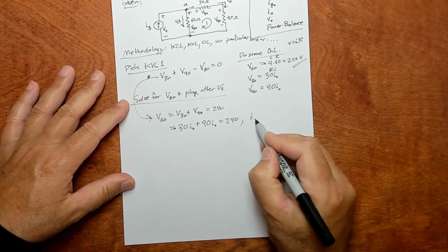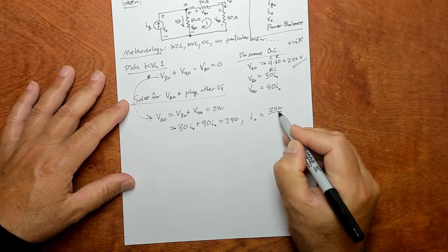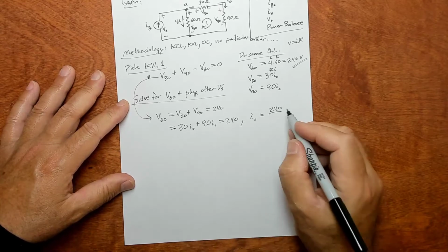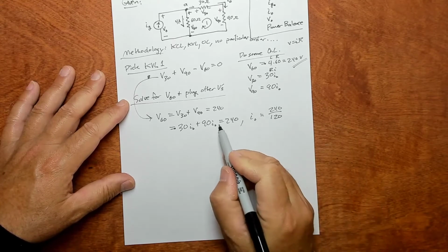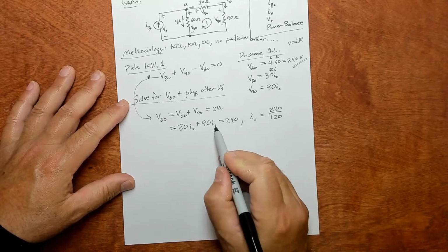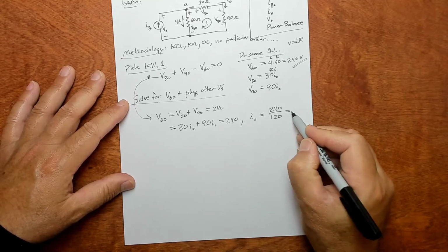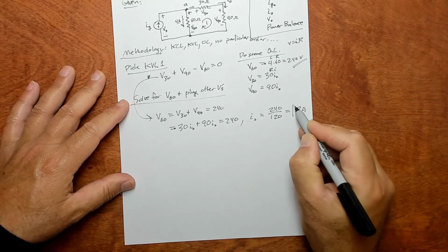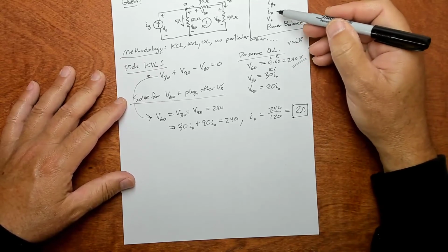So I sub 0 is 240 over these 2, over 120, right? Just factoring out the I sub 0 and then adding the 90 and the 30 and then moving it to the other side, you get this. So it's 2 amps, and that's an answer. So put a box around that, because that's an actual answer that they're asking for.